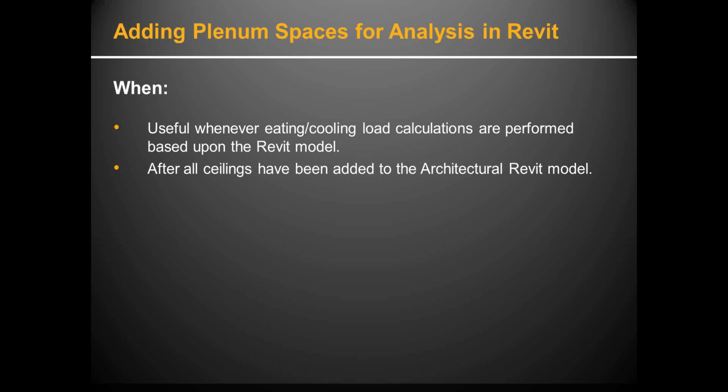When would you add plenum spaces for analysis in Revit? These are useful whenever you're going to do heating and cooling load calculations, whenever they're going to be performed based on the Revit model, whether that's within Revit or the Revit model is exported to something else. And when should you do this?